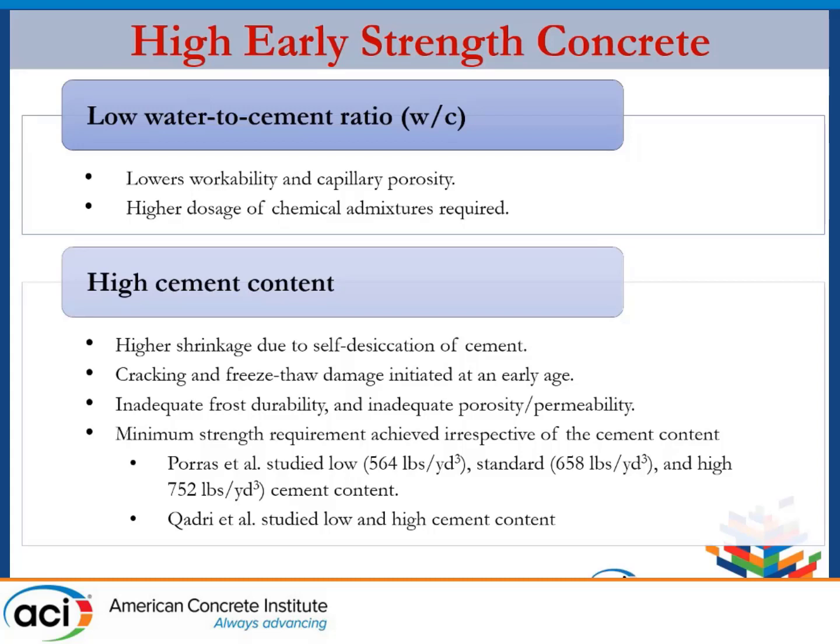This causes cracking and shrinkage at an early stage, which gives way to other deterioration, which is the freeze-thaw effect, where inadequate frost durability or inadequate porosity or permeability is observed in these pavements. So for this purpose, the first part of this project focused on understanding the minimum cement content which will cause the inadequate frost durability.